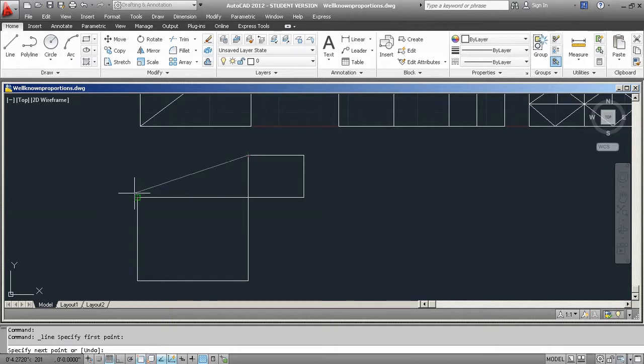Now we're going to create two rectangles, form the two rectangles to make one rectangle out of this using the Object Snap Tracking feature. Object Snap Tracking sees the relationship between where you want to go and where you're coming from and shows the intersection. And enter key. When you see the ghost line or footprint line, you need to show with your cursor where you want to go and where you want the footprint, and then enter key.